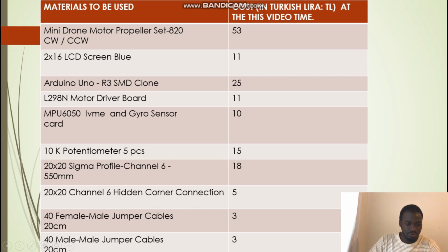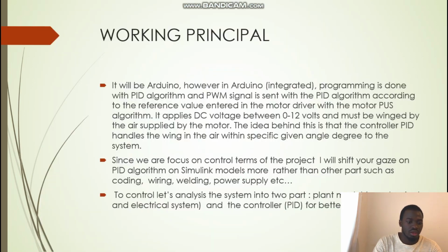Let's go for the working principle. Like I said, it will use the Arduino microcontroller. The microcontroller's integrated programming is done by the PID algorithm, and a PWM signal is sent with the PID algorithm according to the reference input that I said before, entering the motor driver, which amplifies the signal and gives it to the motor.